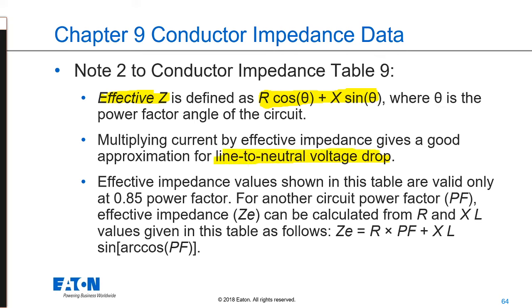And remember what we said, if I'm doing a voltage drop and I'm using the Z, that's the longer part of the triangle. So if I do a calculation based upon that, my voltage drop number will be greater, because my impedance is inflated a little bit, so it's conservative. If I decided to do the R and X and do the long, complicated math, my result is going to be a voltage drop that is less, because my effective impedance will be less than that large hypotenuse Z. So that's another important data point to understand why it's used in the National Electrical Code that way.